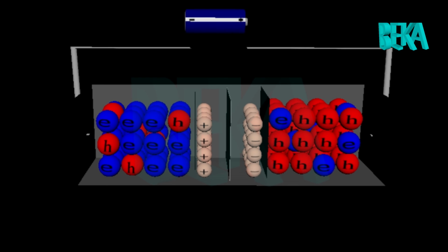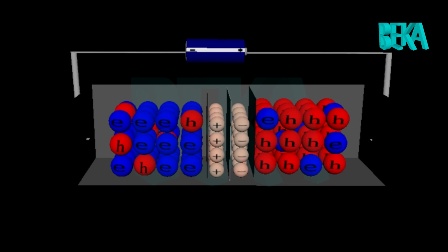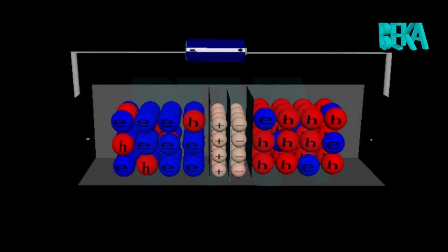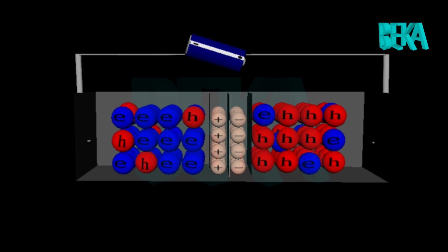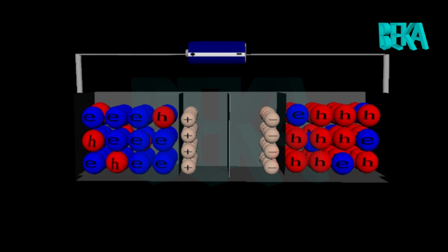If a suitable positive voltage is applied between the two ends of the p-n junction, it can supply free electrons and holes with the extra energy they require to cross the junction, as the width of the depletion layer around the p-n junction is decreased. Applying a negative voltage results in the free charges being pulled away from the junction, resulting in the depletion layer width being increased. This has the effect of increasing or decreasing the effective resistance of the junction itself, allowing or blocking the flow of current through the diode's p-n junction.